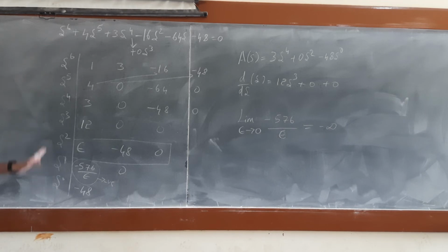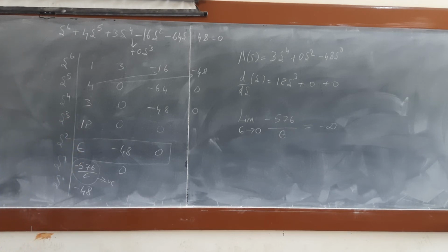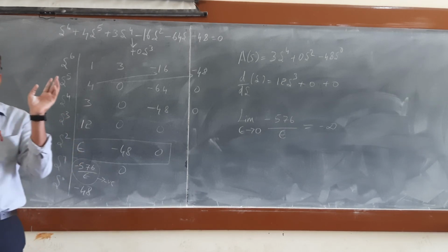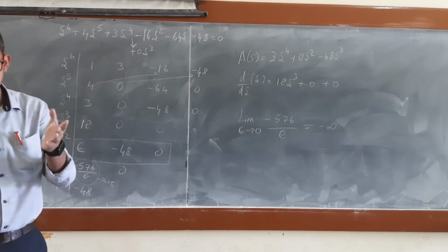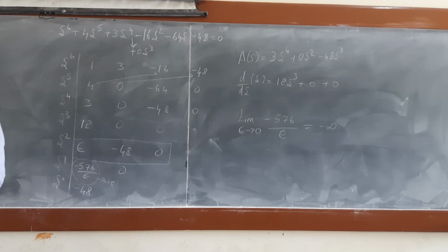The same thing we got. So now what they are telling is we need to find out the number of roots with positive real part, negative real part, and also zero real part. So that is what we need to find out. So here I am going to consider the auxiliary equation. Which is the auxiliary equation?